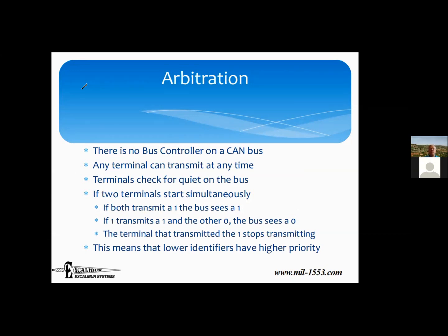Okay, next question is arbitration. And again, this is a question that we have to ask for every single bus. How do I make sure that I don't have multiple devices transmitting simultaneously and making them crash on the bus? So in Ethernet, it's very simple, really, because you never have multiple transmitters on a bus. My device is connected by wire to a switch.